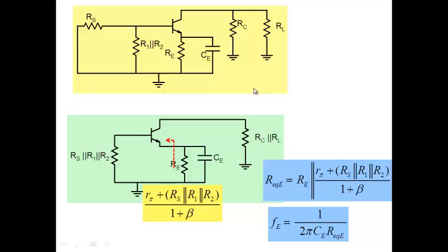So what I've given you is that now the procedure is very general. Any circuit that you're given and you have to calculate lower cutoff frequency, do it one capacitor at a time, find out the time constants, and then if one of them is dominant, that's the lower cutoff frequency. If not, combine all the terms. Okay? All right, so let's stop here.